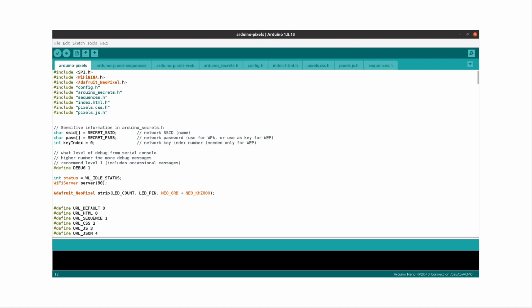If you're unfamiliar with the Arduino, it uses files ending with the extension .ino. These are normally C++ files, but one of the differences in how C++ is normally handled by most compilers is that they're effectively concatenated together at the compiler stage. So this means you can split your program into multiple files, but they're treated as though they're one big file. This is not the way C++ normally works.